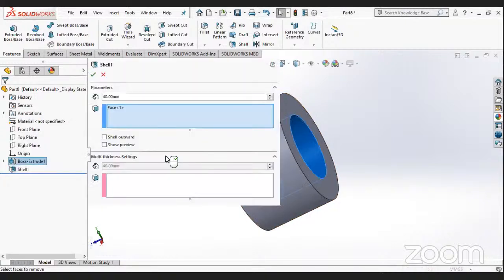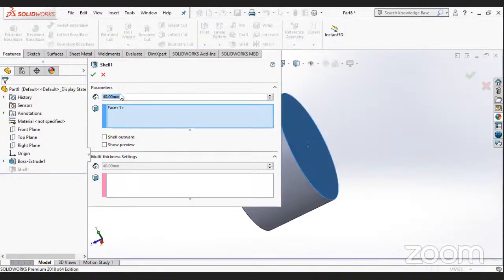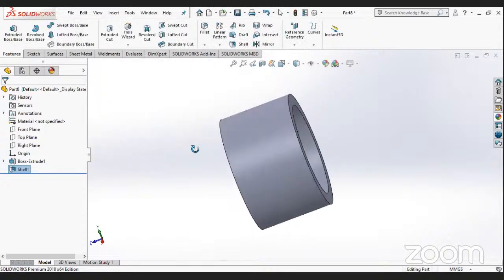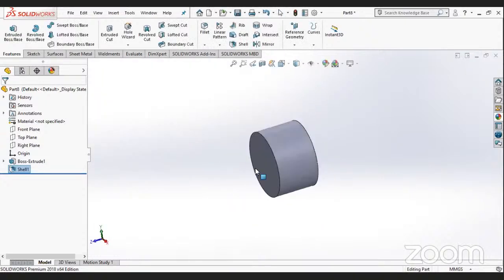We'll quickly edit this from here and make it 20. After making this, we have got an inner shell. We'll quickly make the upper part for this, and the diameter for the same is 160. And the outer one, they have given the thickness as 5. So the other one will be 165.